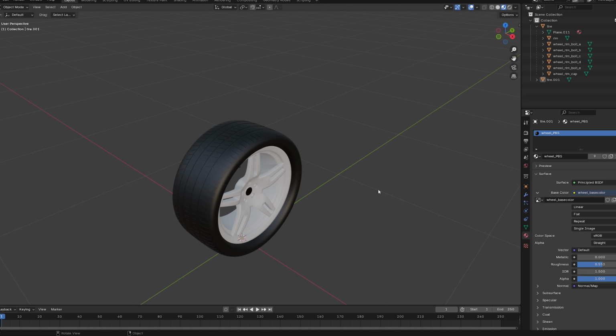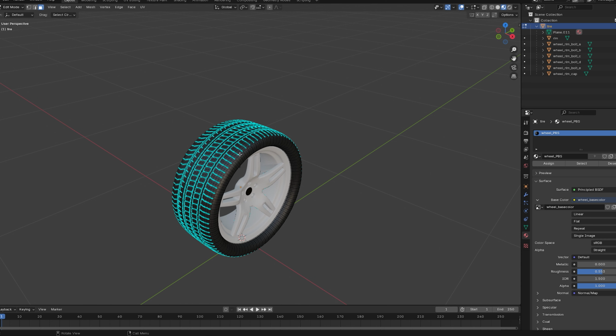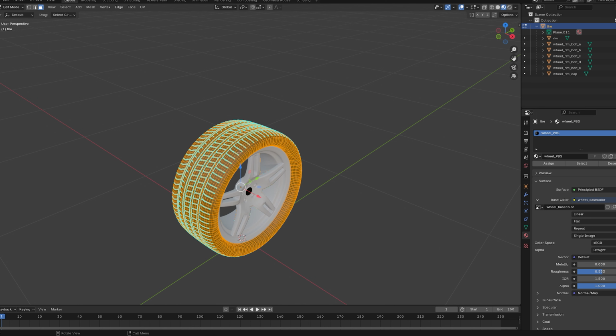To fix this issue, we want to make sure that the detached mesh and original mesh are one object, like so. Now that they are one mesh, now is the time to merge your vertices. So we go into edit mode, select everything, M for merge vertices, and merge by distance. Remove 12 vertices as seen at the bottom here, and it's merged by distance.